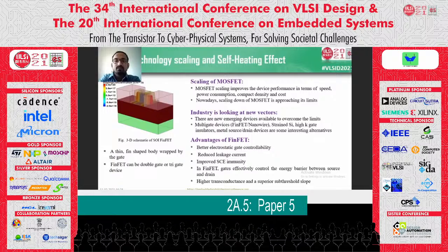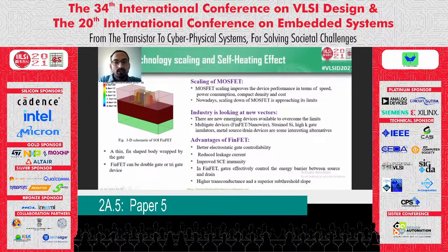FinFET is a thin fin-shaped body wrapped by the gate. It can be either a double-gate device or a tri-gate device based on the thickness of the top oxide. So these are the advantages of the FinFET device: it has better electrostatic gate controllability, reduced leakage current, improved short-channel effect immunity, etc.